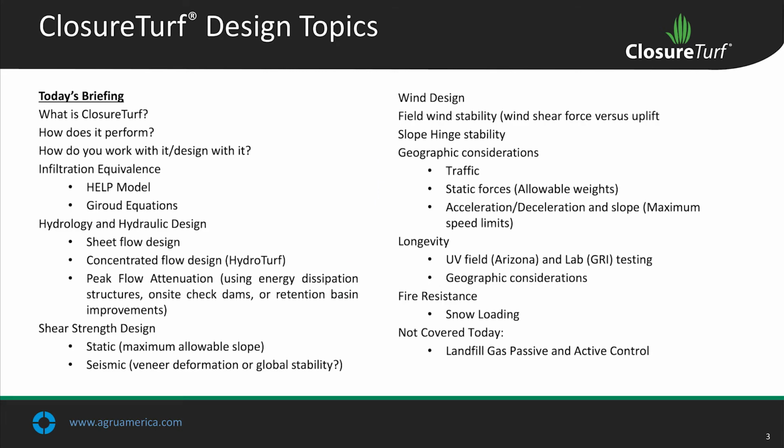Today's briefing, we're going to talk about what is ClosureTurf, how does it perform, how do you work with it, design with it, on things such as infiltration equivalence. We'll look at the HELP model and Giroud equations, hydrology and hydraulic design, sheet flow, concentrated flow, and peak flow attenuation, shear strength design, static and seismic, wind design, field wind stability, wind shear force versus uplift, slope hinge stability